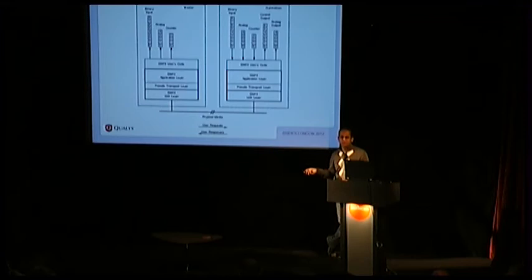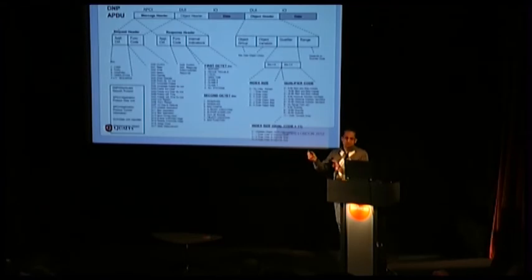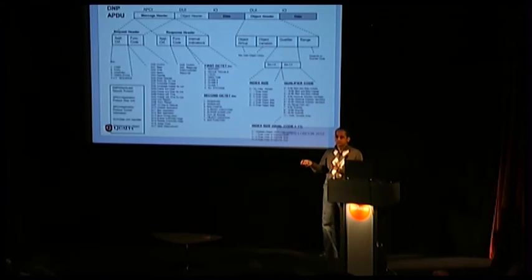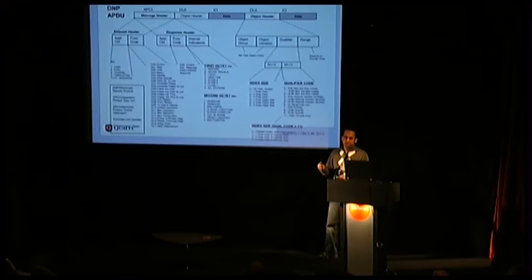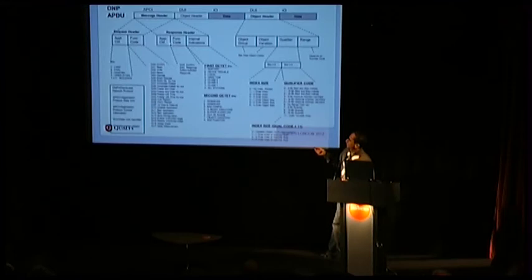It's a 3-layer protocol. It has an application layer, a transport layer, and a link layer. And this is the application layer packet. Again, let's not get lost in the packet details, but it has basically the same thing as Modbus: a server, a client, a request, a response. It has similar function codes, read, write, like what we saw in Modbus.